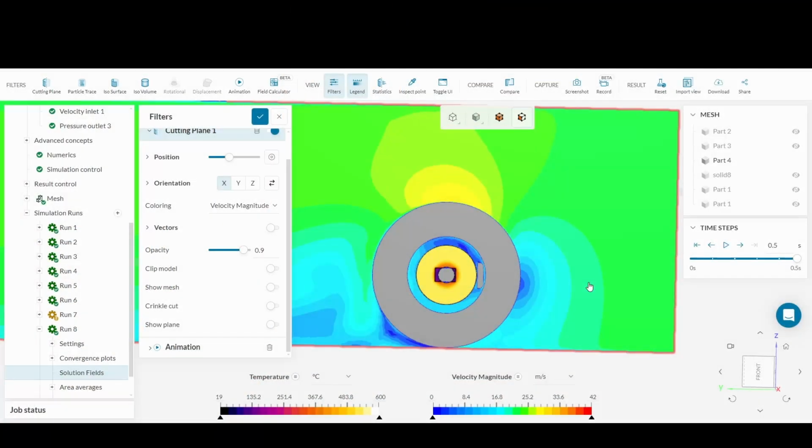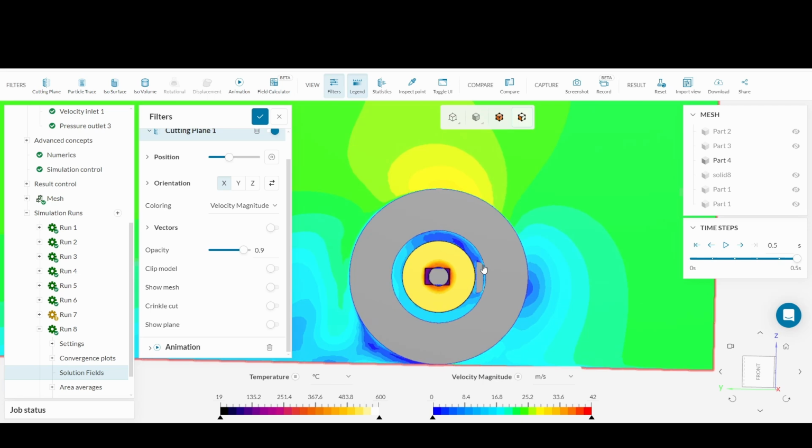So using CFD, you can find the convection coefficient for your brake rotors. It's somewhat advanced, at least for me. I'm not an expert with CFD, so it was a little time consuming to learn this and figure it out. But you can do it using whatever CFD package. It may or may not have a combination of flow plus thermal simulations in there.